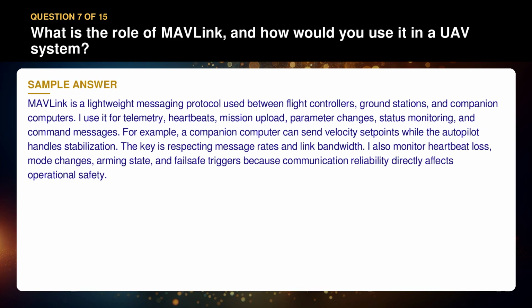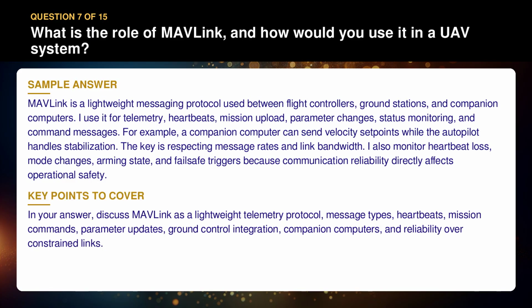I also monitor heartbeat loss, mode changes, arming state, and failsafe triggers because communication reliability directly affects operational safety. In your answer, discuss MAVLink as a lightweight telemetry protocol, message types, heartbeats, mission commands, parameter updates, ground control integration, companion computers, and reliability over constrained links.